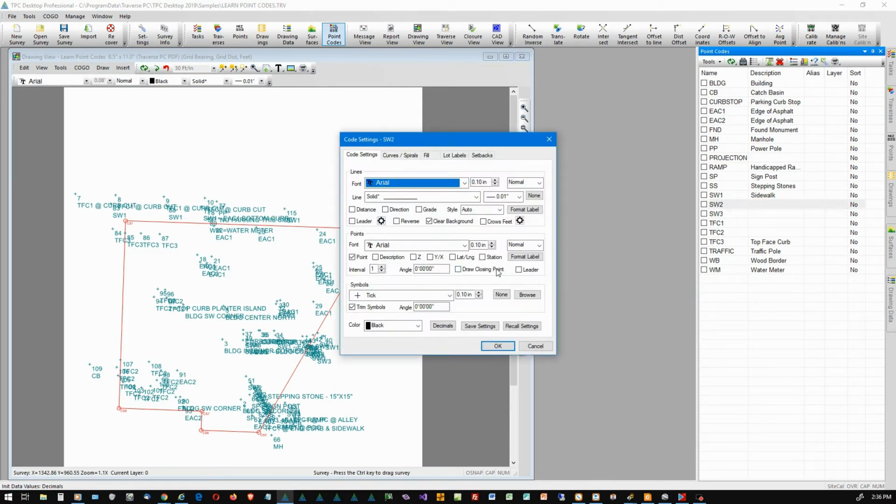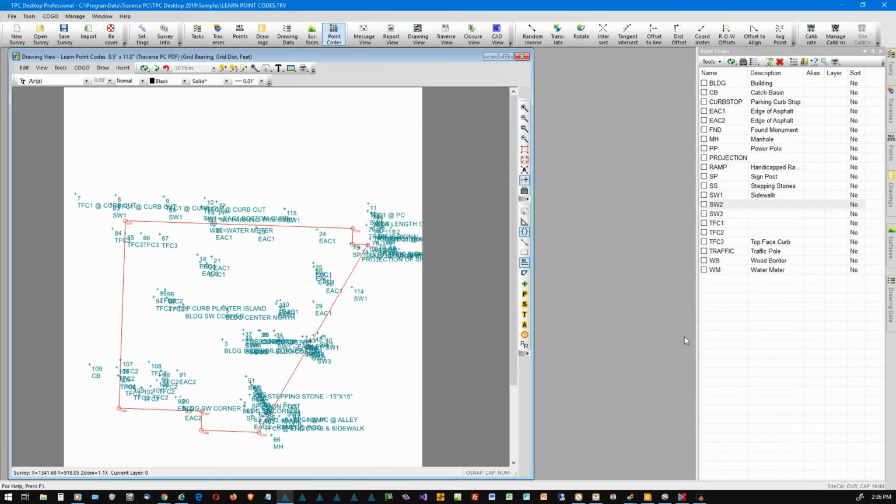So I come in here and take a look at what I've got. Well, right now, a solid line, yeah, it's a sidewalk. Basically, all I want is a solid line. So I don't want point numbers. I don't want any symbols. I just want a solid line. So once I've got this set, I can say OK. So now, the very next thing I do, once I've got that set up, I'll fill in the description so that I know now that I have set that one up. All right?